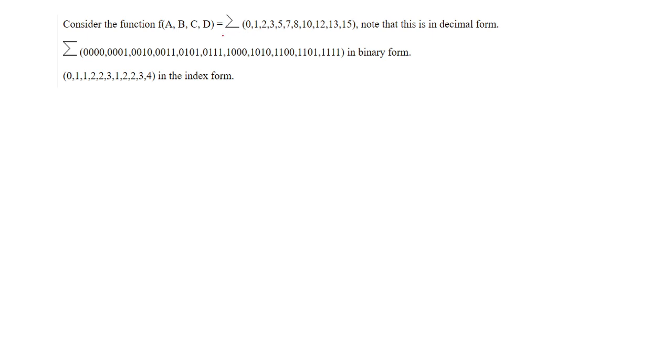For the given problem, first we have to check that it is a 4 variable problem. So you can cross check the final result with the K-map also, since it is 4 variables. A 4 variable K-map is easy for finding out whether the result is correct or not. So better we do it using the tabulation method and cross check your result with a 4 variable K-map.